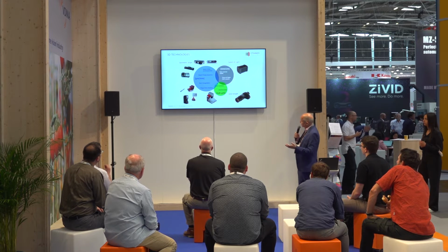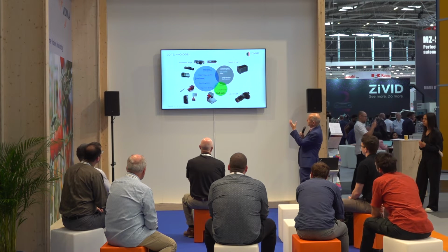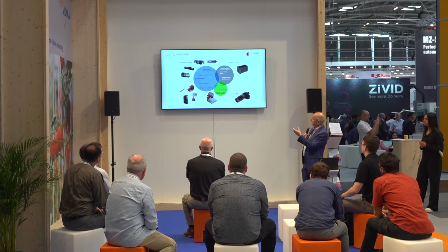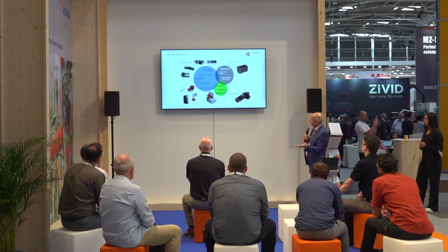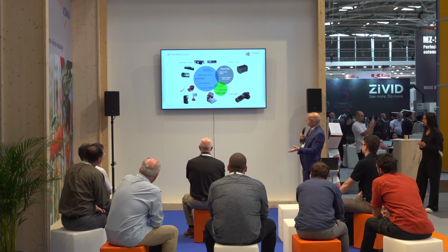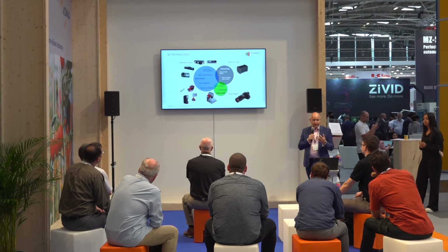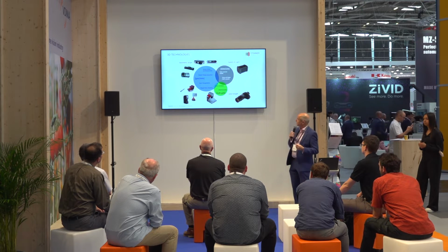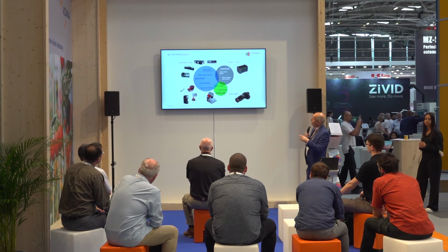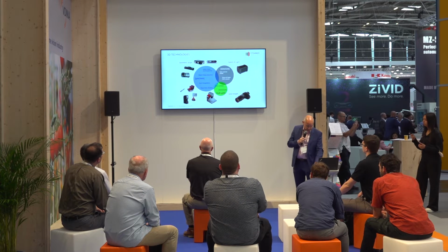So we have technologies that can go from probably centimeters with things like time of flight, LiDAR, stuff like that, down to millimeters and microns with stereo and laser triangulation. And then we can even get down to sub-micron accuracy with confocal, interferometry and stuff like this. So it really comes down to what you're trying to achieve, to determine which is the right camera technology to apply.